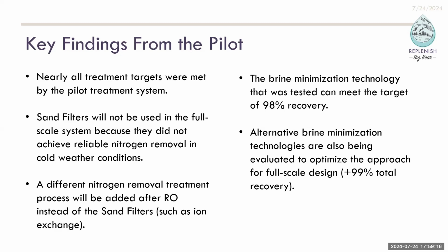Top right there, we did meet our 98% recovery target. As Lane clarified and mentioned, the brine minimization, the salt we piloted through IDE, did the job and exceeded that 98% recovery at 98.7%. What we do want to look at are brine minimization technologies for full scale design, to see if we can get more water recovered above that 98.7% we achieved, and see how that compares for cost and other considerations as well.